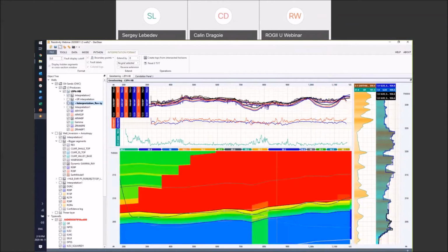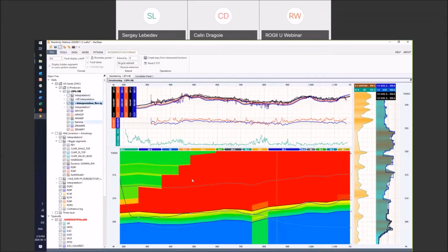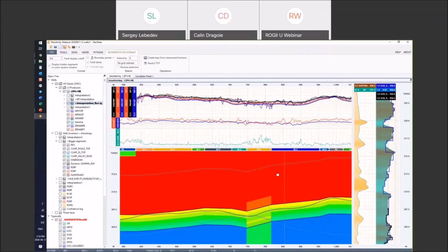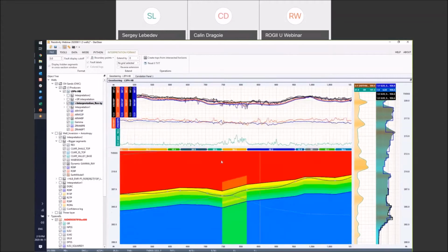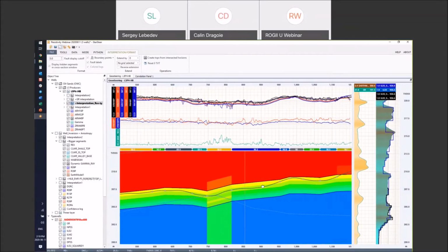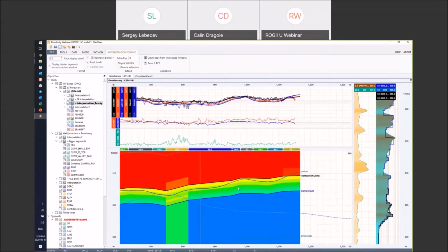Here's the better one. So here's a very good interpretation. I have the resistivity profiles from low to high resistivity. Here's perfect matching. Here I added some other layers in order to achieve the resistivity values due to high gamma content. Okay.